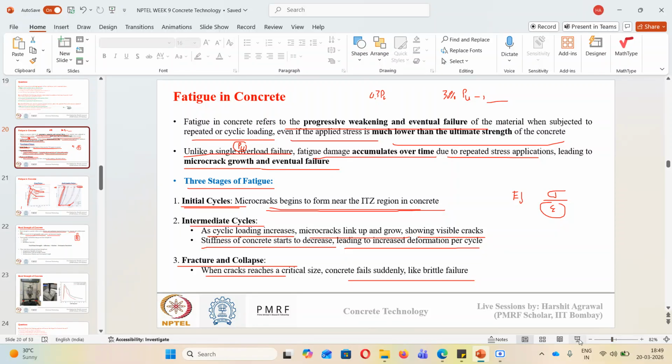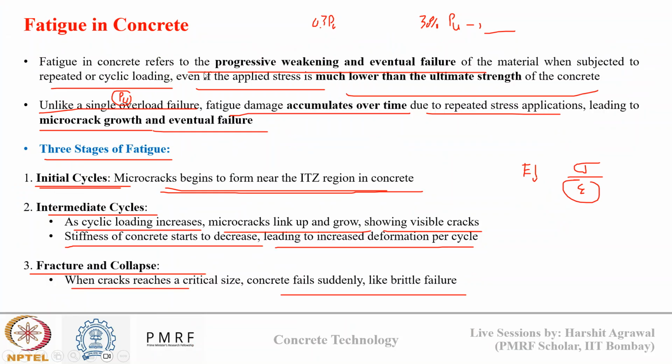So on this slide, I was talking about what is fatigue. Fatigue is when I'm applying a smaller quantity of load but for a longer time. When I apply a small load for a longer time, the cracks accumulate over time due to repeated stress application, and this leads to failure of concrete. And this failure is known as fatigue.